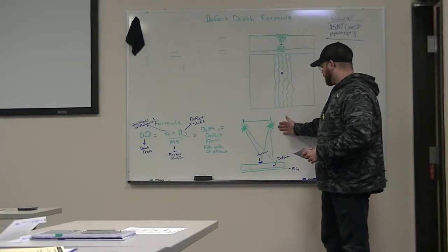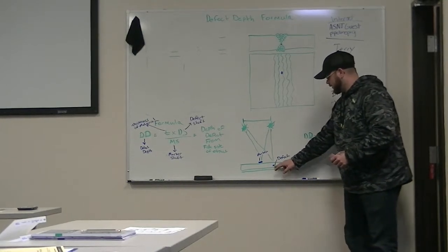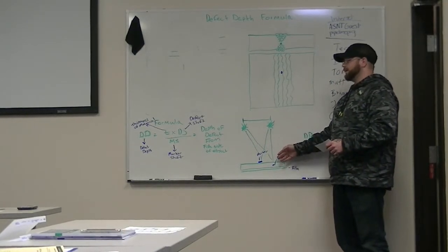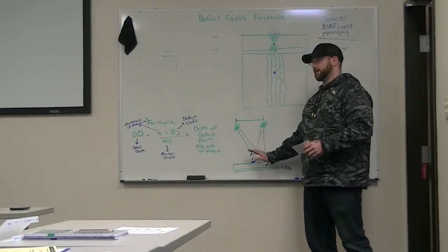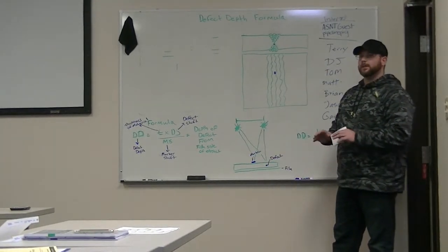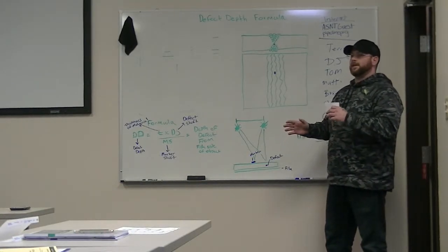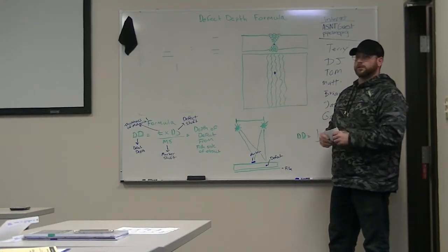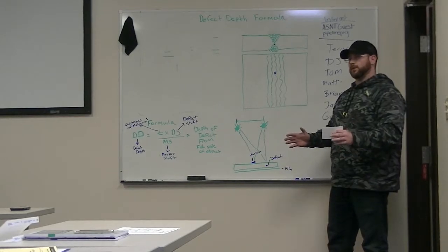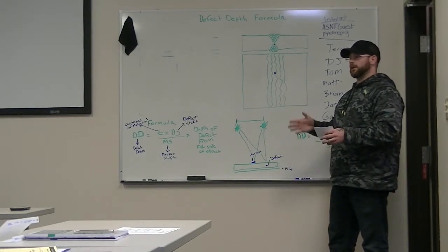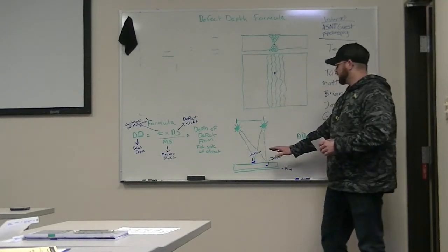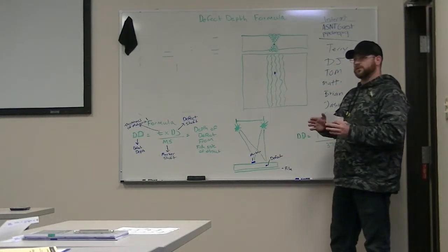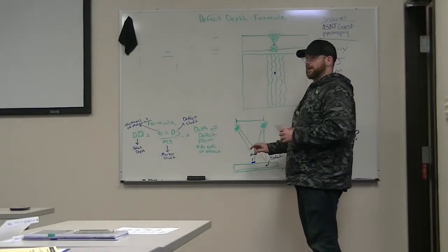Over here is an example of the method we would take to produce such a radiograph. We take one shot with a marker on the plate, and you know your defect. One shot at an angle. You adjust your tube, take a second shot. We're going to use the same film, but it's going to be applied with a half exposure. So whatever it takes to create one exposure on a radiograph, we're going to cut that in half, shoot it half the time, adjust the tube, and then shoot it again. And that'll give us the shift in our defect and in our marker.